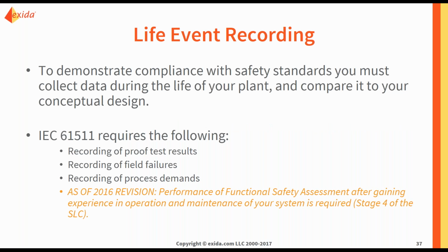Here we have to do life event recording. To demonstrate compliance with the safety standards, you must collect data during the life of your plant and compare it to your conceptual design. During SIL verification, you had specified proof tests, their intervals and effectiveness. During analysis, you assumed failure rates and the frequency of process demands. So this is something you want to record as your plant is running.